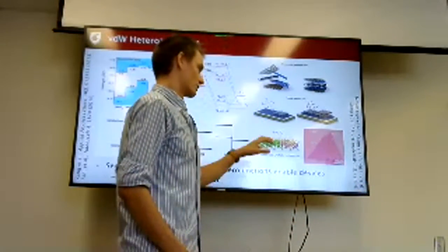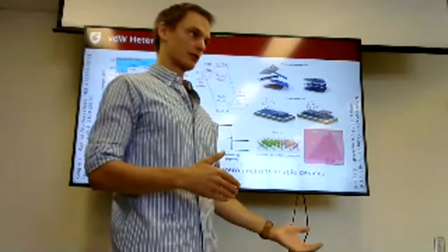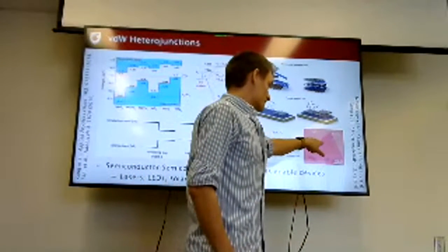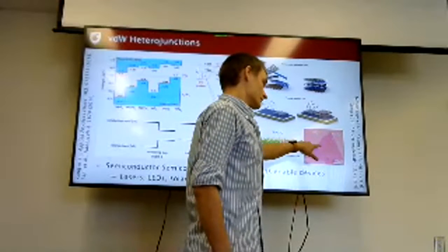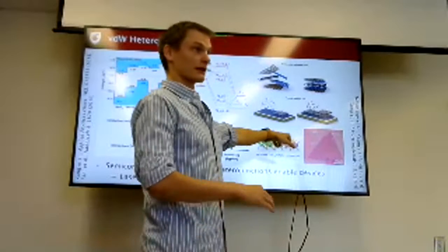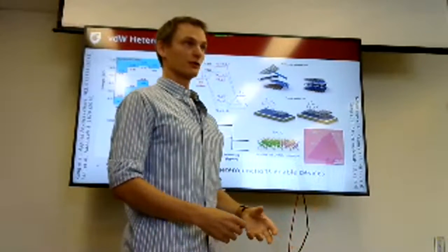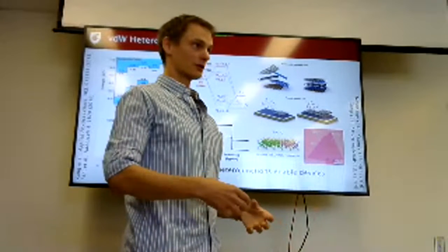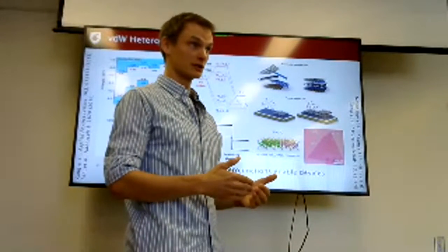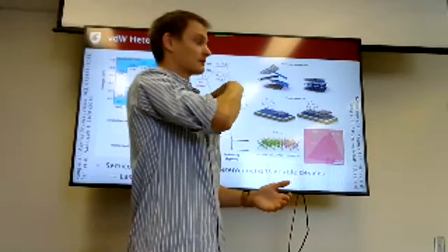So a lot of focus has been put on growth methods. And the idea here is that we would either grow a vertical or a lateral junction. So this paper, what they grew was MoS2 in the center and then WS2 on the outside. And the specifics of those don't matter. What matters is that they grew a heterojunction, right? That was in plane. There's a lot of problems with this, right? Crystal growth is a difficult thing on its own. Controlling nucleation sites is difficult. Getting the crystal structures to align is going to be difficult. So there's a lot of problems to overcome in these methods.